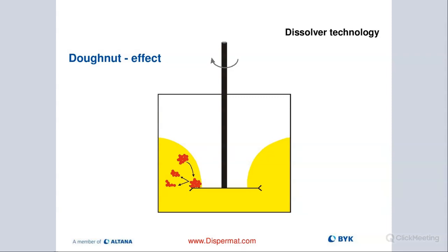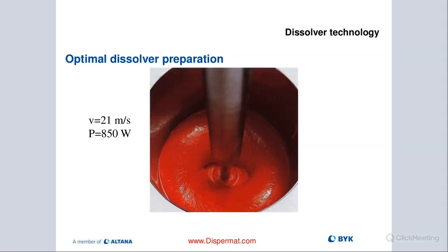So this is what's happening. The blade actually has these teeth, these edges on the edge of the blade. These teeth are popping up on the bottom of the blade. That's where all the shearing is happening, and that's what's causing the breaking up of these binding forces. Optimized, that will create the donut that you ideally want to see when you dial all the parameters into the process.